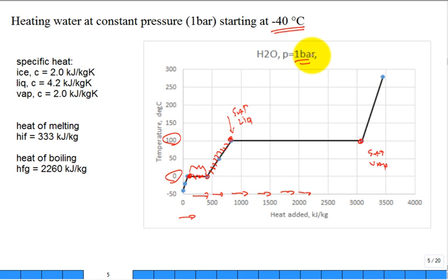It's the boiling point. This is something that throws students for a loop. They can't figure that out. They'll make the mistake conceptually. What happened? The temperature stayed the same. Well, then you couldn't have added heat. If you added heat into it, the temperature is going to go up. Not if it's changing phase. Not if you're either boiling it or melting it.